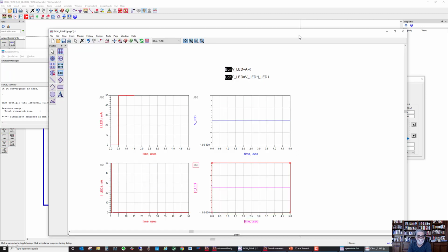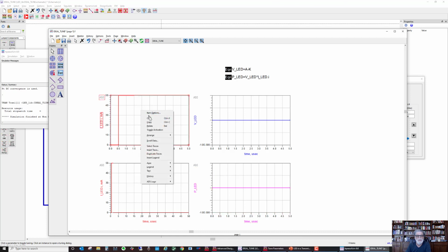And you'll see it looks similar now, where halfway through the line we get up to 50 milliamps, and then that lasts up until we get to the reflection both directions of the line. And then I should be able to, there you go, show you what it looks like at 100 milliamps. And so that 100 milliamps now is because we have a short at the other end of the cable. So now we see the 5 volts divided by just the 50 ohm resistor. And you can see in the midpoint, we're right in between.